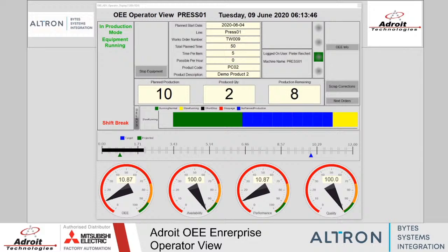I'm going to produce just another one, and another one, and you will see the dials didn't move. The dials will not move because the dials only move at the end of a block period. So if your block period for information has been set to 5 minutes, it will wait 5 minutes in the beginning, then it will react, and then every 5 minutes it will update to give you the new values.